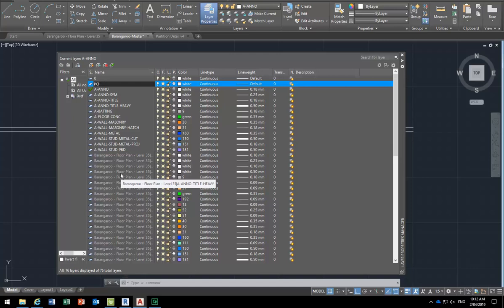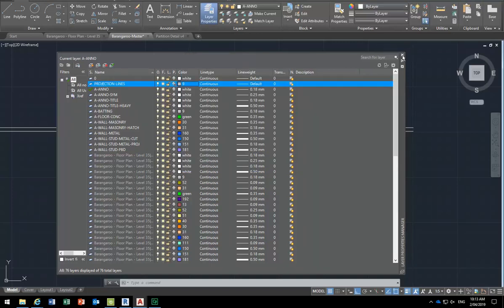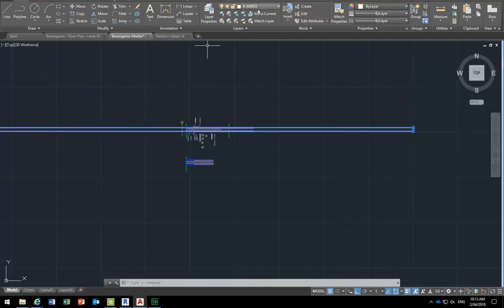Oh yes, project, projection lines. Normally I wouldn't even type in all of that, but I'm going to set it to be non-printing. And then I'll make the colour maybe grey, and maybe make it current layer, so then I can put these lines onto that layer.